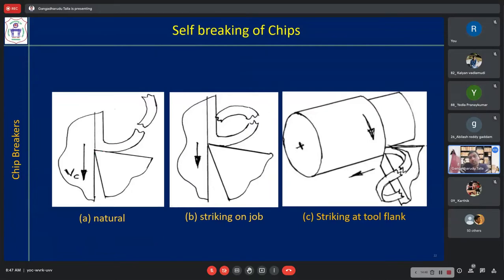So the side which is not in contact with the tool will cool faster. It is freely subjected to the flowing air outside, so it will cool quickly, and the other side will take more time for cooling. So there is non-uniform cooling on either side.